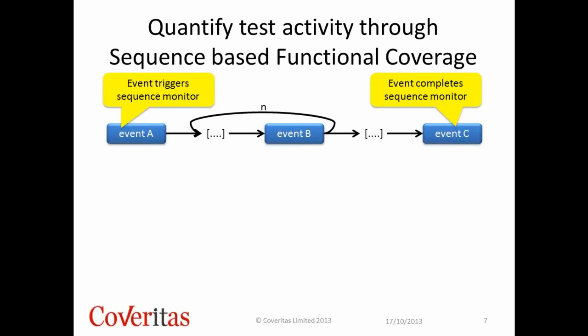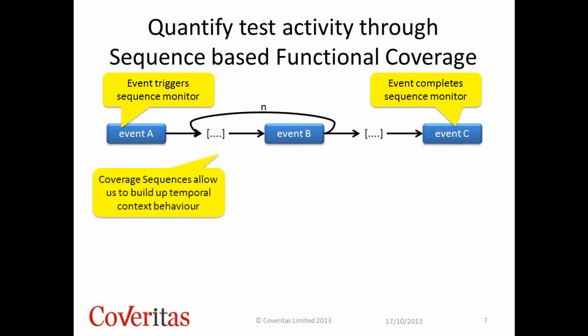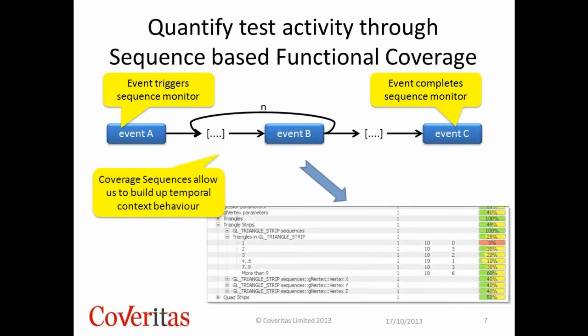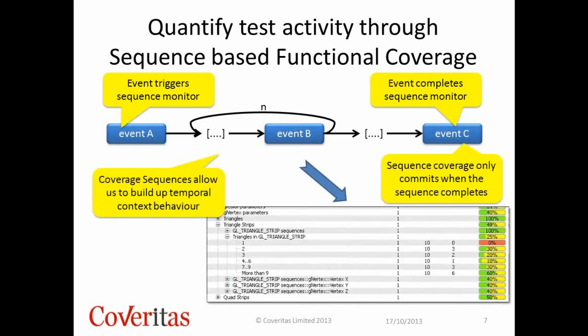So what we're doing now, rather than taking a use case and writing a test, we're taking a use case and writing a coverage model for it. And that coverage model will tell us when our random tests actually hit that scenario, and maybe it didn't hit that scenario. And then this data can all go into a database. Databases are good at this stuff, and we stick it into an SQL database, which can then be mined for all sorts of great information about what you've done, what you haven't done, what you used to do but you no longer do, all those good things.